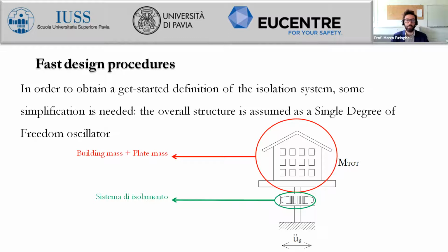So this means that at the end of the short course we will be able to model the proper hysteretic loops for all the typologies of devices that we have considered up to now: rubber bearings, lead rubber bearings, and curved surface sliders. I will provide you very fast and easy to implement rules which are able to describe the proper hysteresis of the overall force response. And we will be comparing all the displacement and the force response.